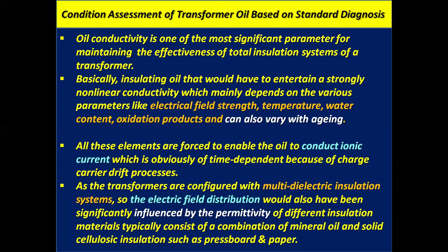As transformers are configured with multi-dielectric insulation systems, the electric field distribution is also significantly influenced by the permittivity of the different insulation materials, which typically consist of a combination of mineral oil and solid cellulosic insulation such as pressboard and paper.